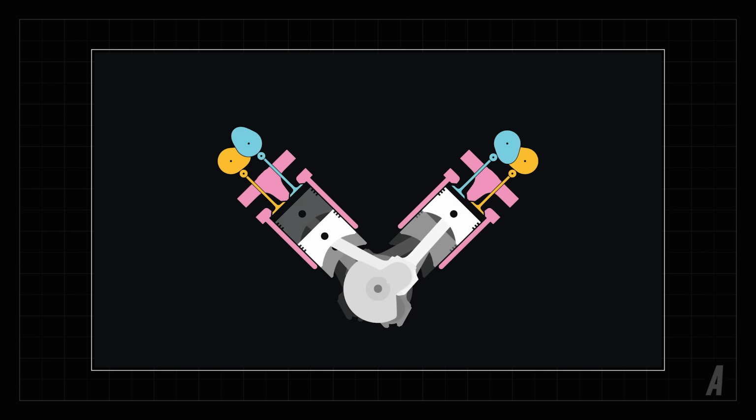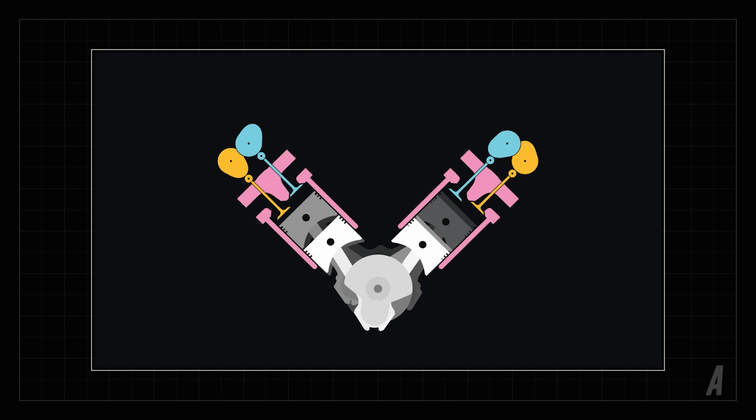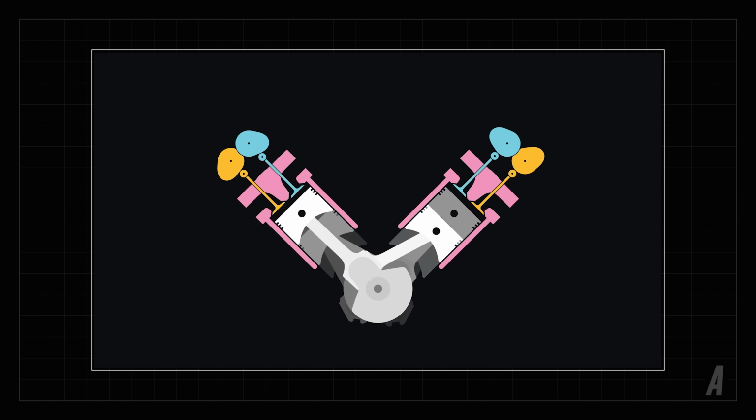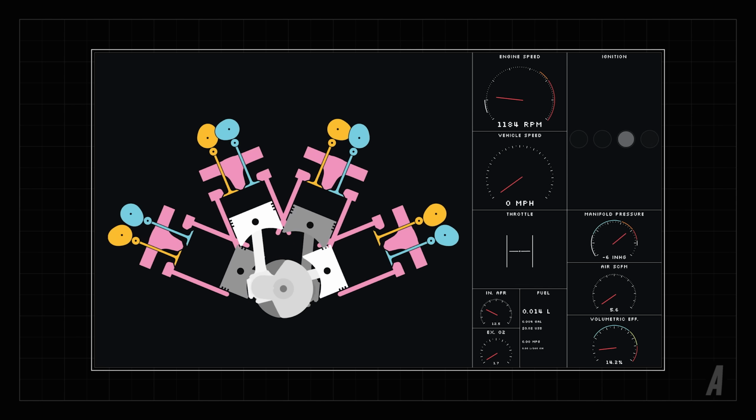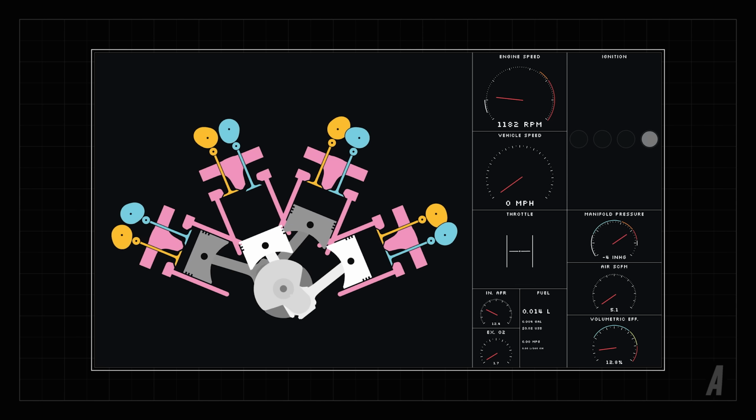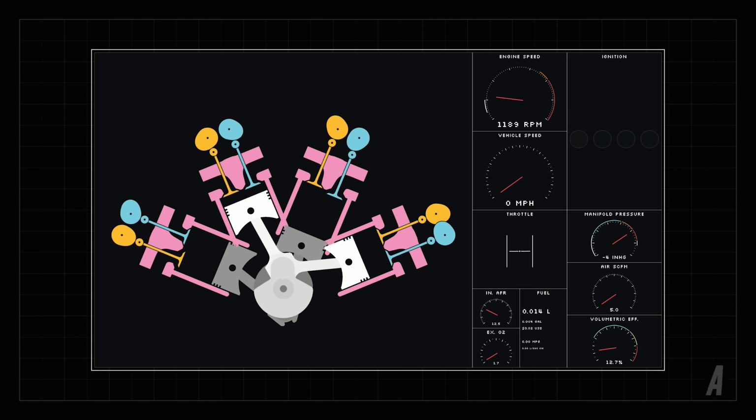trumpet. The most challenging aspect of Engine Simulator is the requirement that it runs at or near real time, which seems to rule out a lot of the more advanced fluid simulation techniques. In fact, just running in real time isn't even enough because we need to also generate real-time audio, which is usually sampled at 44 kHz or higher. That means we need to run the fluid simulation at least 44 kHz, or we'll start sacrificing audio quality. Most physics engines in games run at the game's frame rate or a little bit higher, so 60 to 200 Hz. Some games with more sophisticated simulations like BeamNG can run at around 2 kHz.